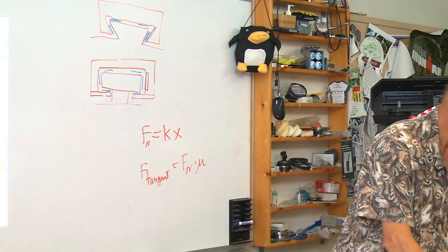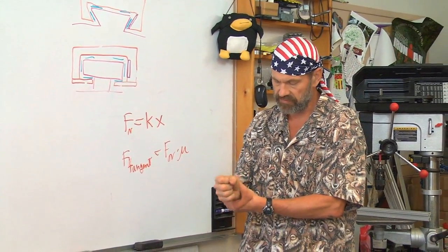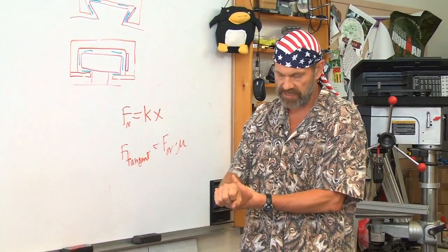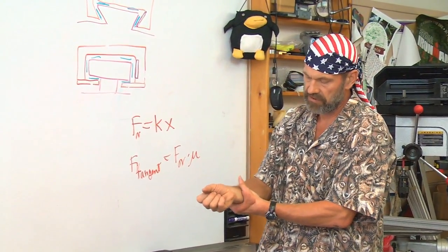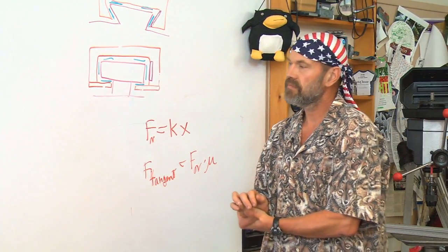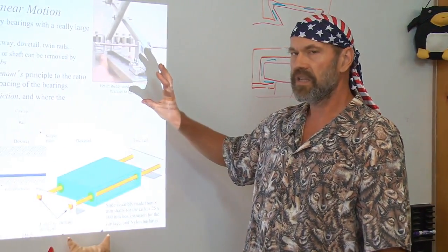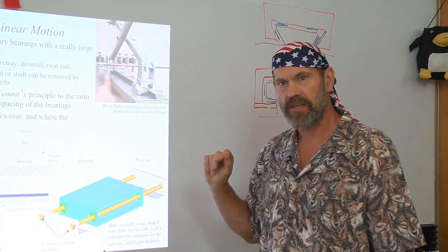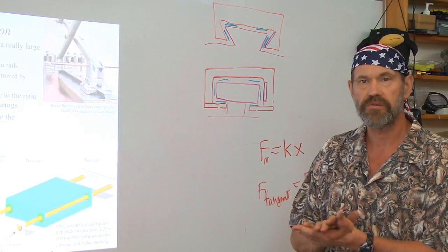How do you design a bearing to last in a construction site? A rotary sliding contact bearing is relatively easy to make last with a rotary seal. But for the linear motion, how do you avoid dragging dirt in? Very important topics. One of the nice things about sliding contact bearings is they in general tend to be very tolerant of dirt.